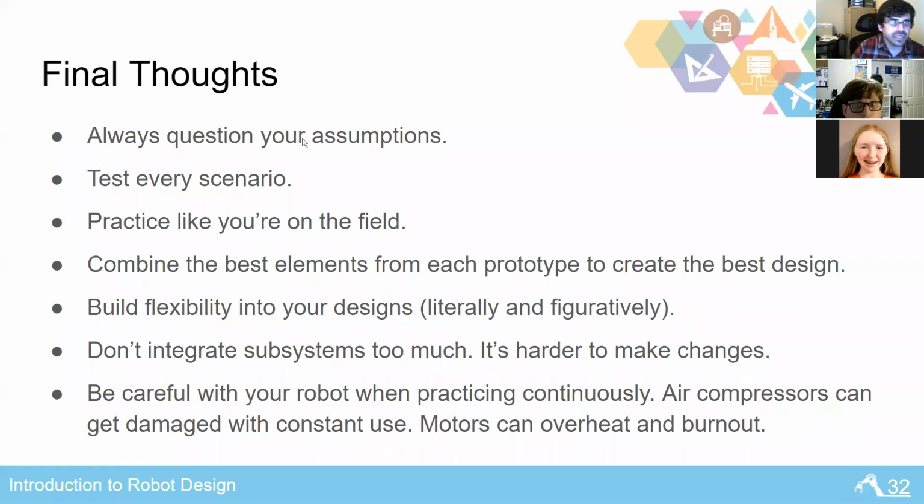The bad thing is to say that you understand how something works and that you're not going to test it, because that's when you break on the field. It definitely happens to us more than I like to admit. But we definitely want to test every scenario. We want to test it like it's a practice. So we want our drivers not looking over the robot as they're moving the controls, but back behind the driver's station just so that they are getting used to lines of sight. They're getting used to really what a match will be like.